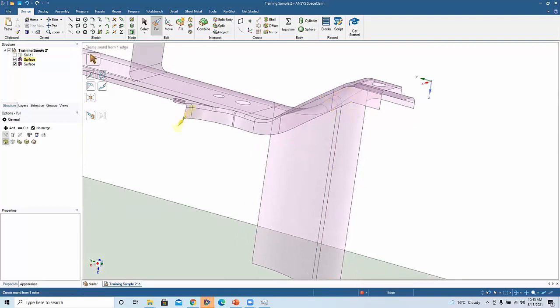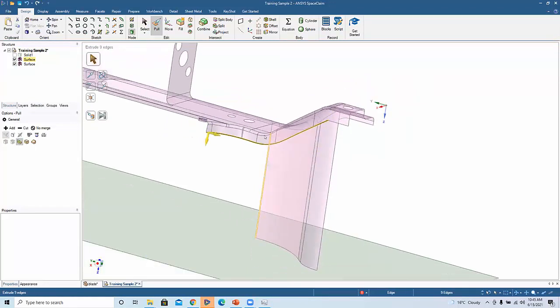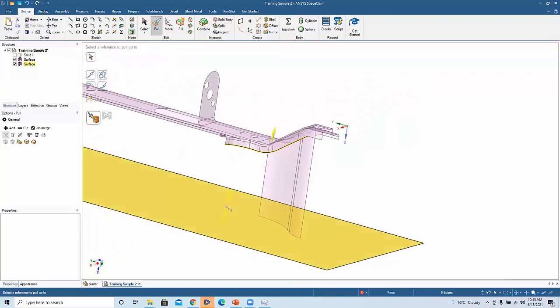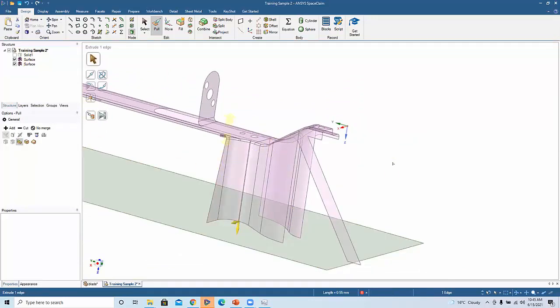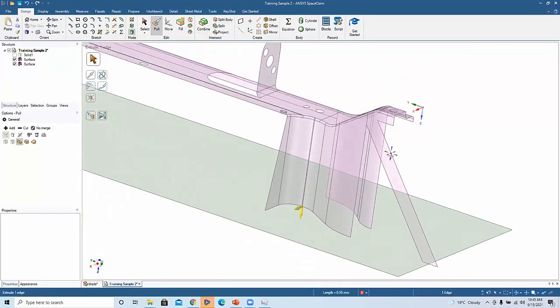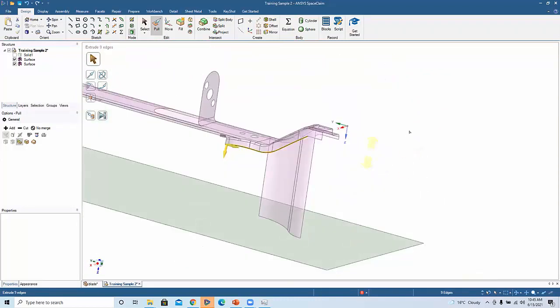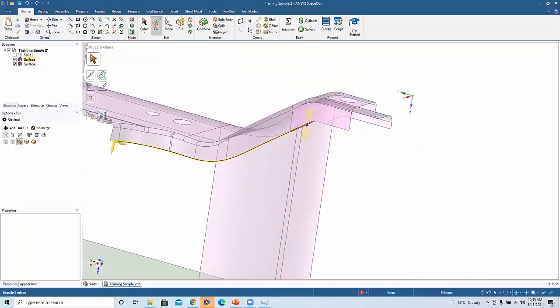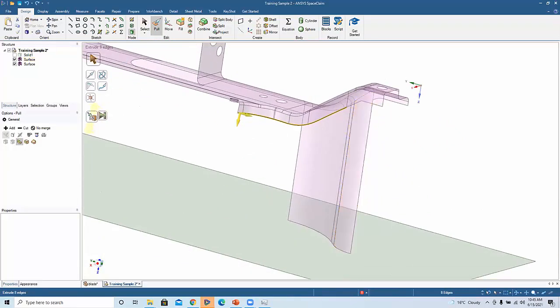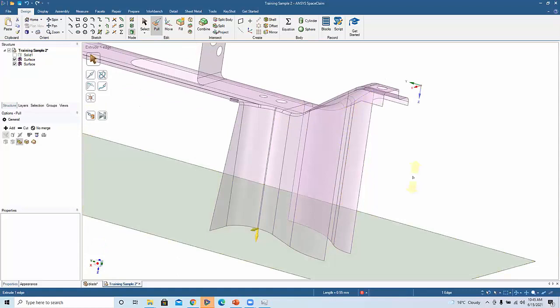So you'll notice that I had some problems with that other edge before, because it had trouble with this particular corner. Now when I click on the UpTo, having deleted those rounds, it still has that problem. If I still have that issue, not a problem. What I can do is remove that from the selection and click on the UpTo.